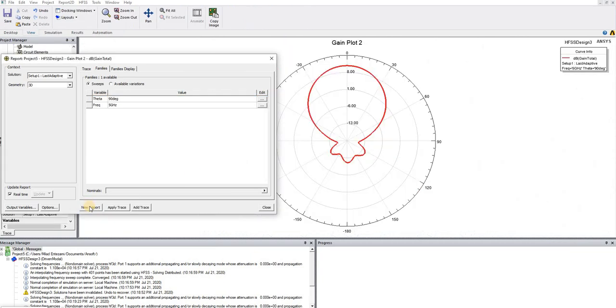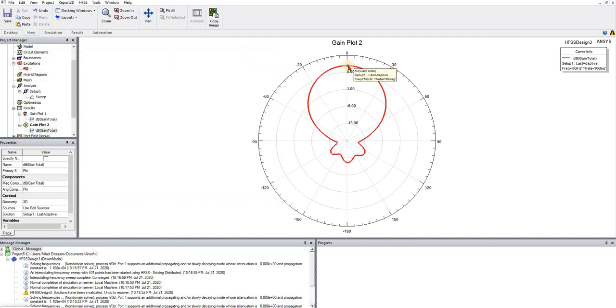Okay, here you can see the H-plane of this antenna, and if you add a marker here, you can see the gain is equal to 10.5 dB. As you remember from the last lecture, the gain of the 4-array microstrip antenna is equal to 12 dB. So this is a single element and this is a high gain antenna. Also we can see another result.